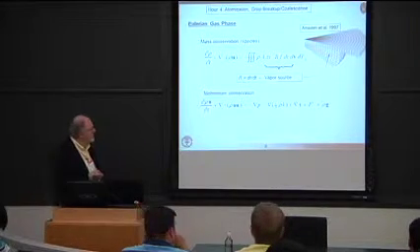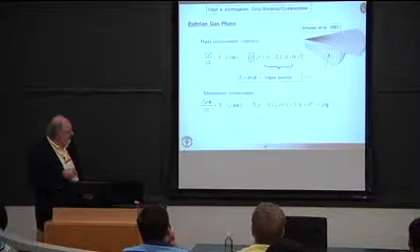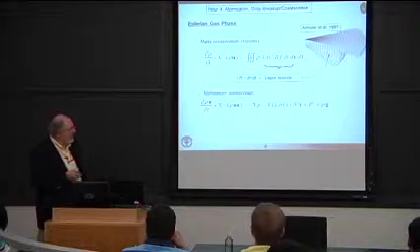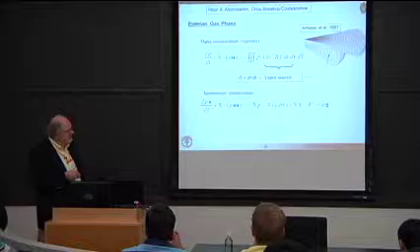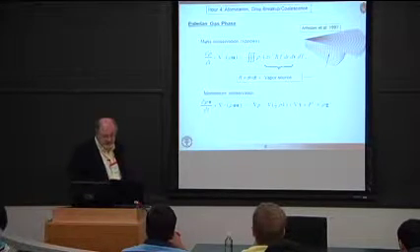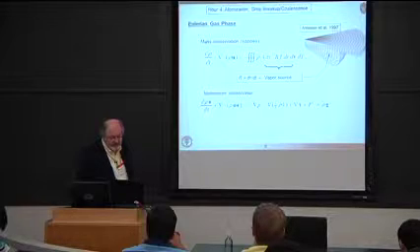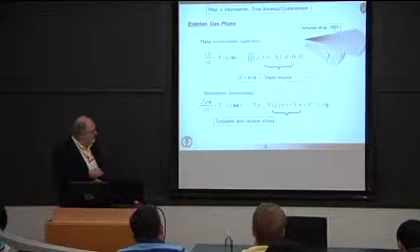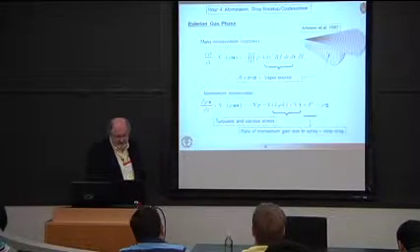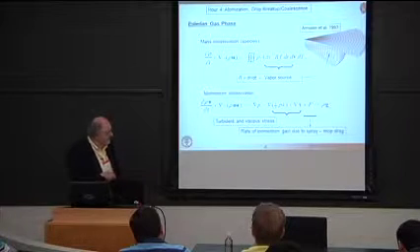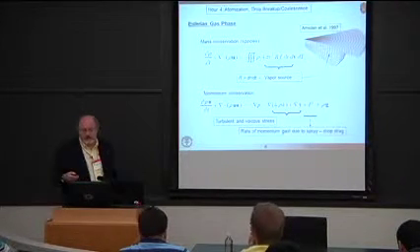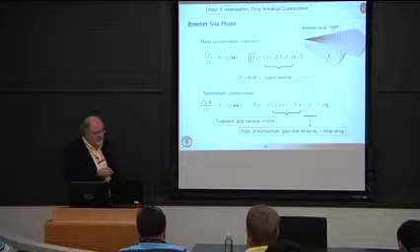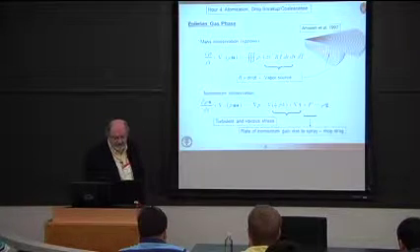Similarly, if we look at momentum conservation, here's our Navier-Stokes equations, which I'm sure you've seen. This term here, F, corresponds to a momentum exchange term between the spray and the ambient gas. And we need to be able to specify that. So if we look at the equation, we have our general viscous and turbulent stress terms, and then this source term, which is the rate of momentum gain due to the spray. So basically, as droplets slow down due to drag, that momentum is transferred to the gas, and this is the term that does that. But we still have to specify what that term looks like.